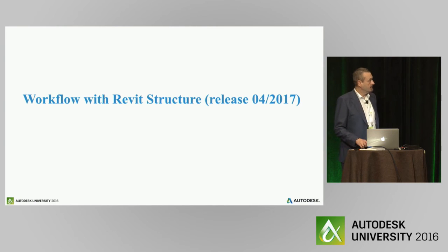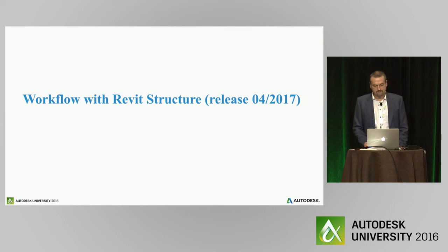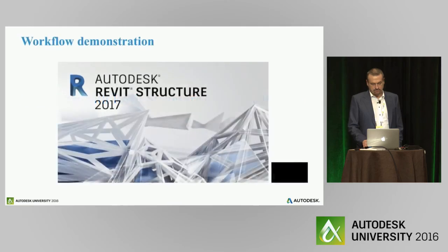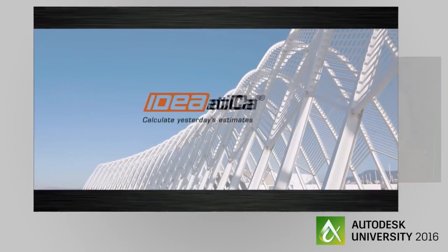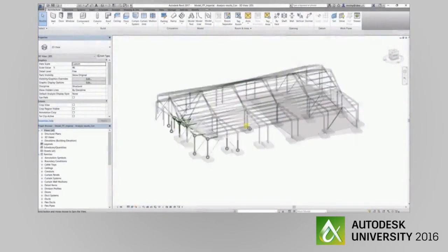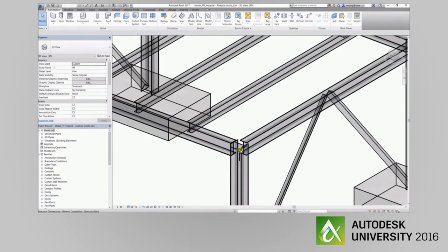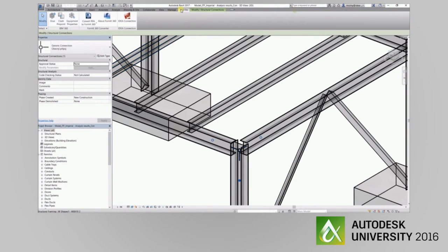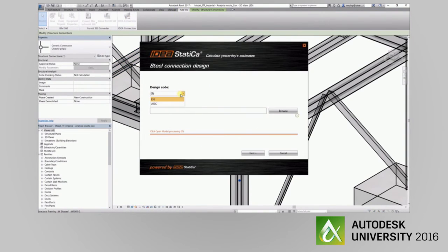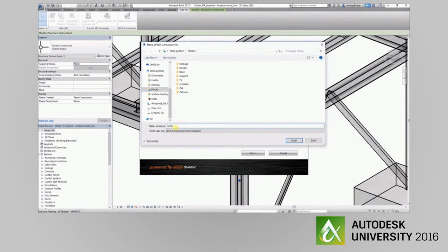Now we can continue with another workflow with Autodesk software, which is Revit. It's a quite new development, which is not completely finished, but we can show this also. There is the structure in Revit. In Revit, the difference from other FEA software is that there is an object called connections. You can define a connection directly in Revit. Define means the node and all connected members.